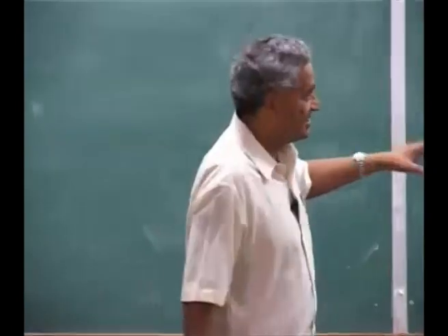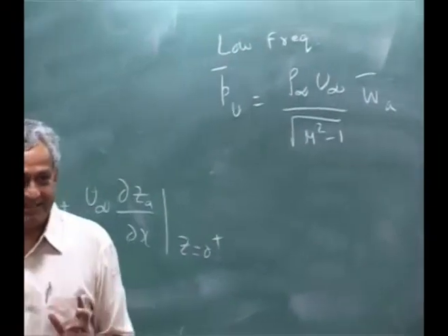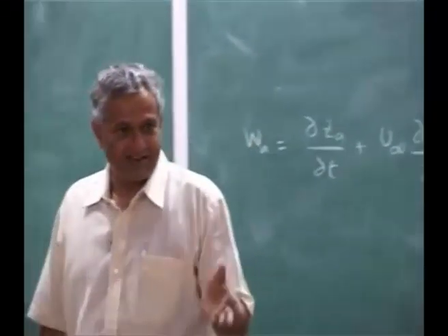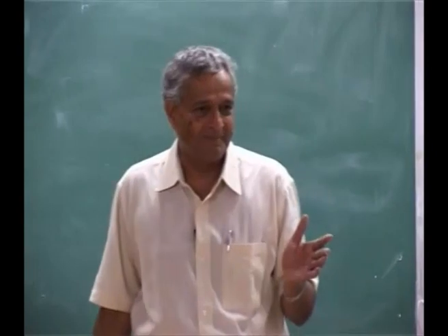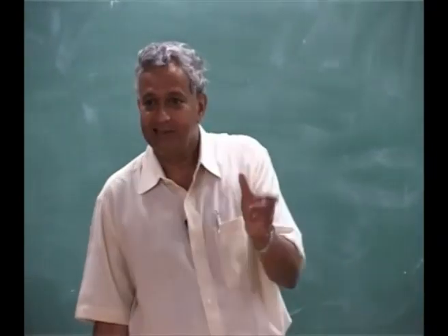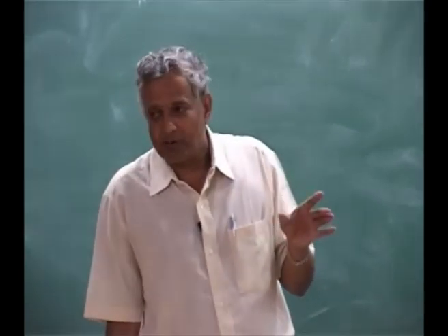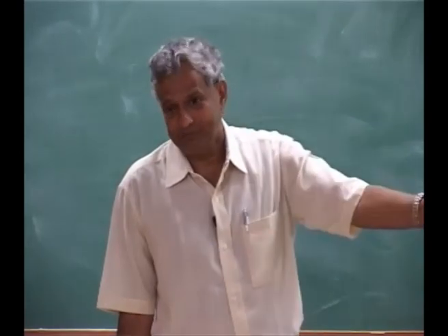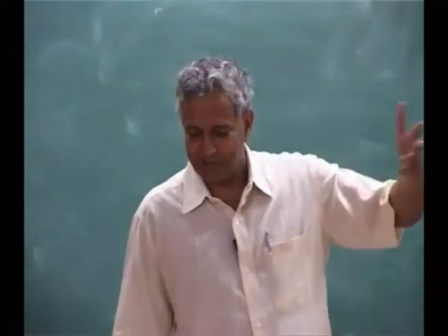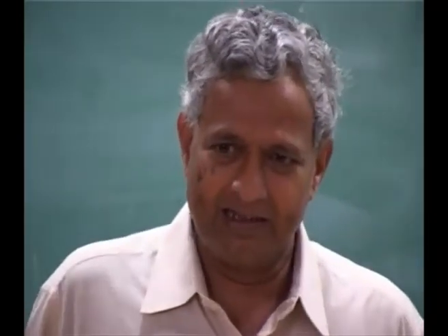Here you are giving directly only the factor and the motion, h dot, alpha dot, you directly put it there. If you use the exact expression with no approximation for omega, then you will start having the complex number. So basically you will solve the flutter problem by complex eigenvalue theory. Actually a complex eigenvalue problem you have to solve, but that we will learn at a later part.